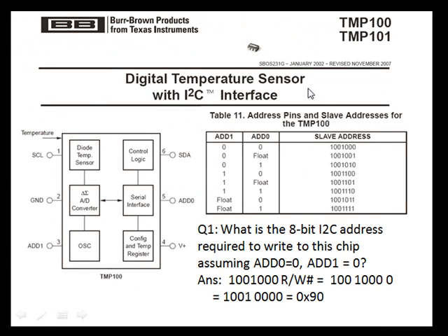One of the beauties of the I2C interface is that its generic format allows you to interface new devices fairly easily just by reading their datasheet particulars. For example, here's a datasheet for a TMP100 temperature sensor. If we wanted to use this device, the first question we want to know is, what would be the unique I2C address that we could use for this device?